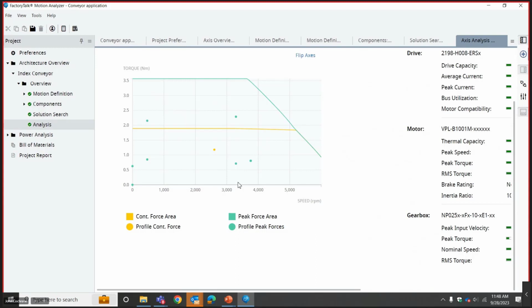The zone above the yellow line is your intermittent zone. For brief accelerations or decelerations, the servo motor can operate above 100%, 200, 300% for a brief period of time. However, if you start doing that too often, your RMS torque will start going up on the application.